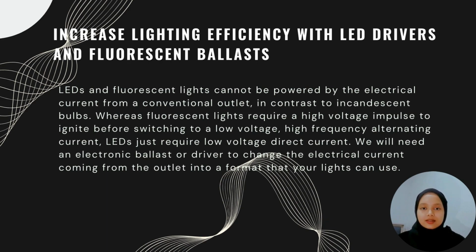Okay, for increased lighting efficiency with LED driver and fluorescent ballast. LED and fluorescent light cannot be powered by the electrical current from a conventional outlet, in contrast to incandescent bulb, whereas fluorescent light requires a high voltage impulse to ignite before switching to a low voltage, high frequency alternating current. LED just require low voltage direct current. We will need an electronic ballast or driver to change the electrical current coming from the outlet into a format that your light can use.